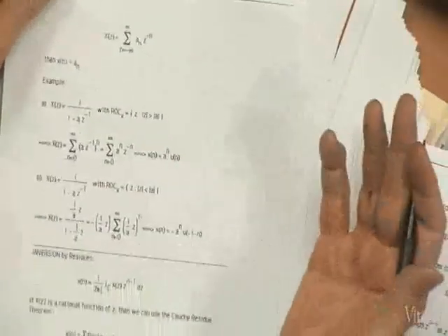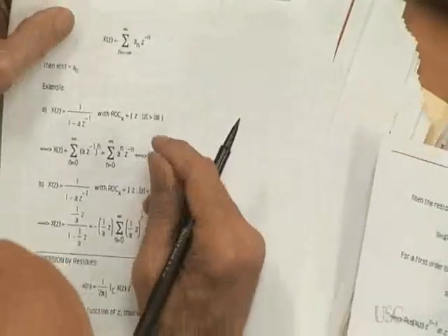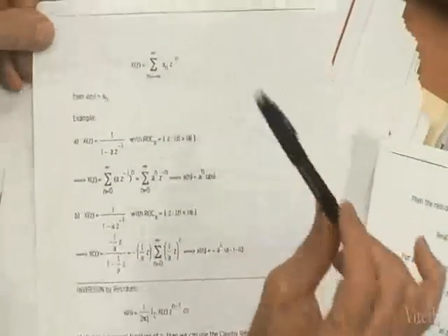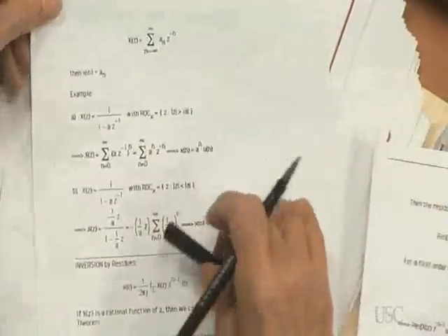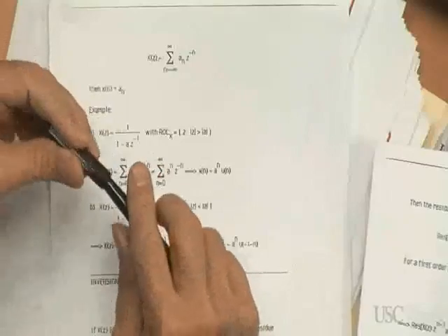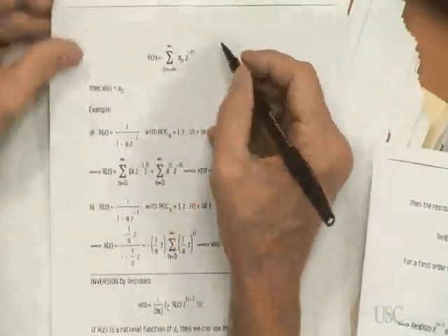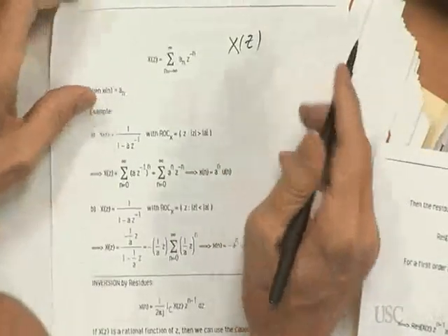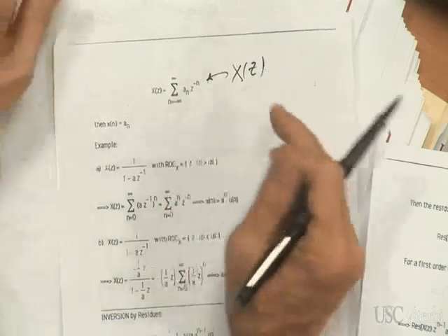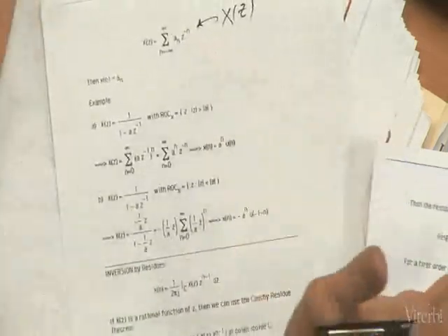But generally, there are several ways of doing inverse Z-transforms, and we picked the easiest ways, all right? We don't have to do it very often, because there are tables that you use. There's no point in memorizing the tables. But to give you a little insight, one way to do an inverse Z-transform is this: if I give you a Z-transform X(z), plus the ROC of course, and I can expand X(z) in a power expansion of z, involving both positive and negative powers of z, then done.